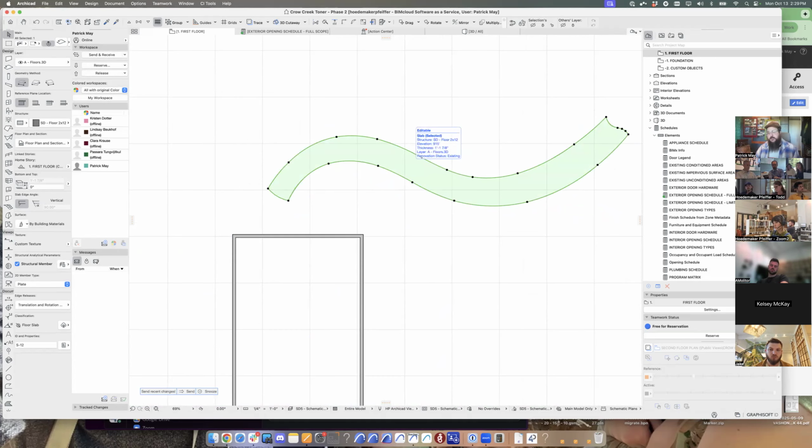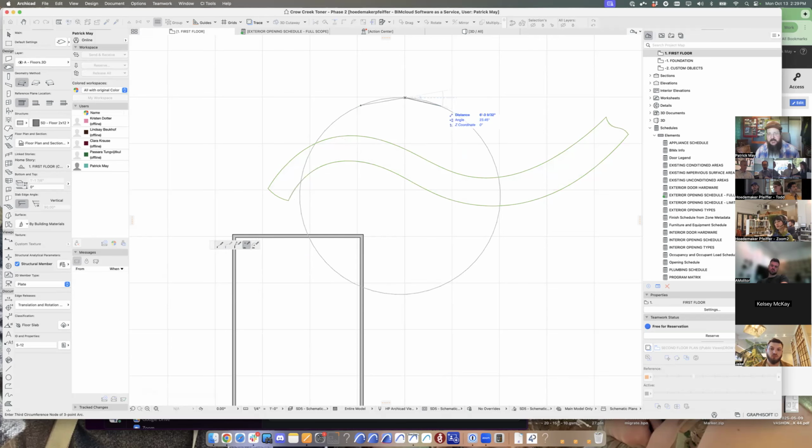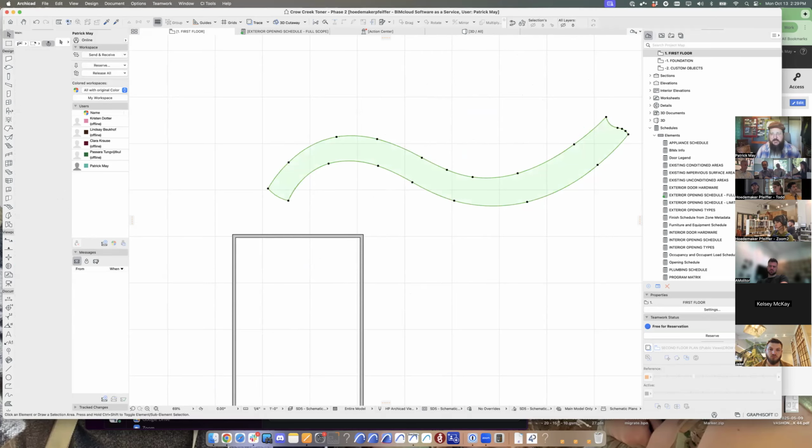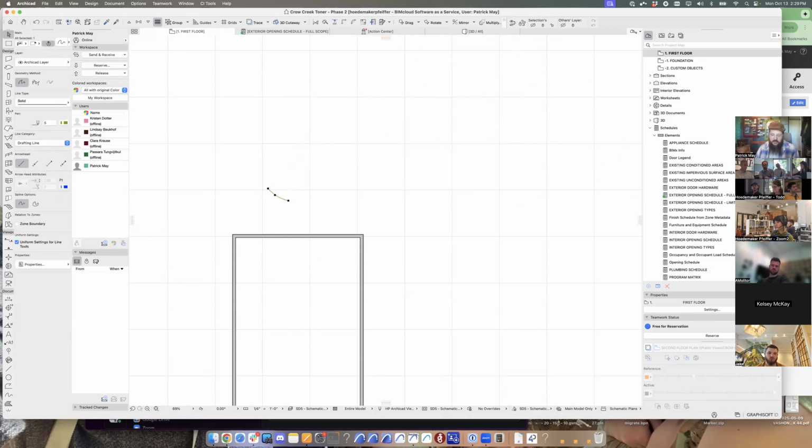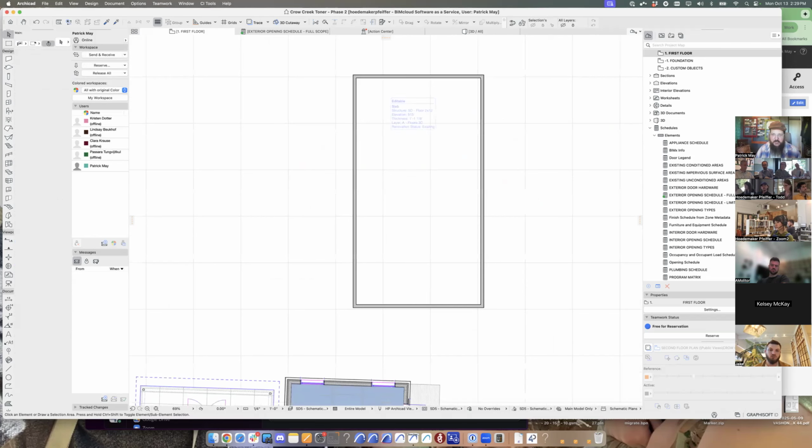Getting that shape with tangents based on a polygon slab, you can do it, I can take tangents and try to guess at that and get close, but the spline tool is way better at that because it's always going to find the smooth tangents. So again, using the right tool for each job is an important step.